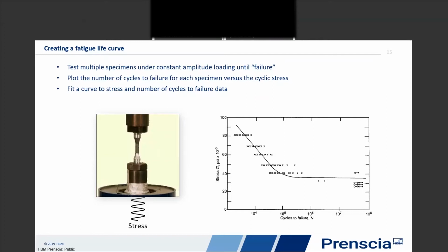Now, the curves that we create here talk about the actual alloy itself, but are missing other things that would be in our parts. Things like possibly the mean stresses, the residual stresses, the surface finish. So all this additional information, we go in and we tack onto the performance of our material curve to go off and try to make that curve simulate our part.